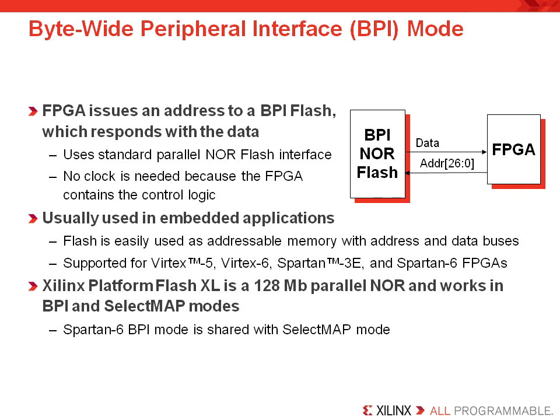As you can see in these cases, no clock is needed because the FPGA contains the control logic. As an FYI, a NAND flash memory is a different technology. FPGAs do not configure directly from NAND flash memories. Note that the flash device can also be used in embedded software applications where it may be necessary to store a system's software in a flash device, as well as the FPGA's bitstream.